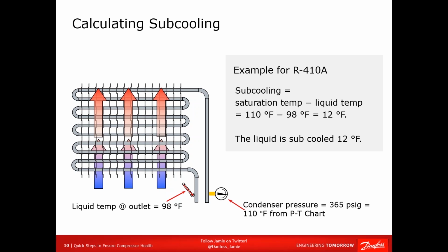But we don't come out of the compressor at that temperature. We might come out at 170 degrees. All right, superheated. At least you better hope it is. So we're going to hit this condenser and we're going to cool down because the refrigerant's hotter than the surrounding air.